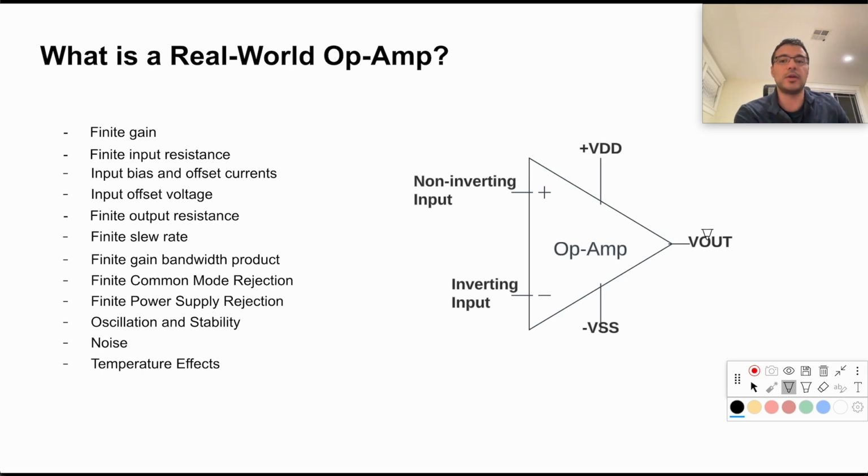Typically, the one that we are most concerned about is the input bias current. This is generally the most important thing about these op amps because they have the ability to truly affect a huge voltage gain on large resistors if large resistors are used in negative feedback configurations. The second most important, well, it's kind of hard to say what is most important, but the things I have come across as most important are the finite gain bandwidth product as well as the input offset voltage. We're going to get into questions regarding all three of these topics, but before we move on to interview questions,